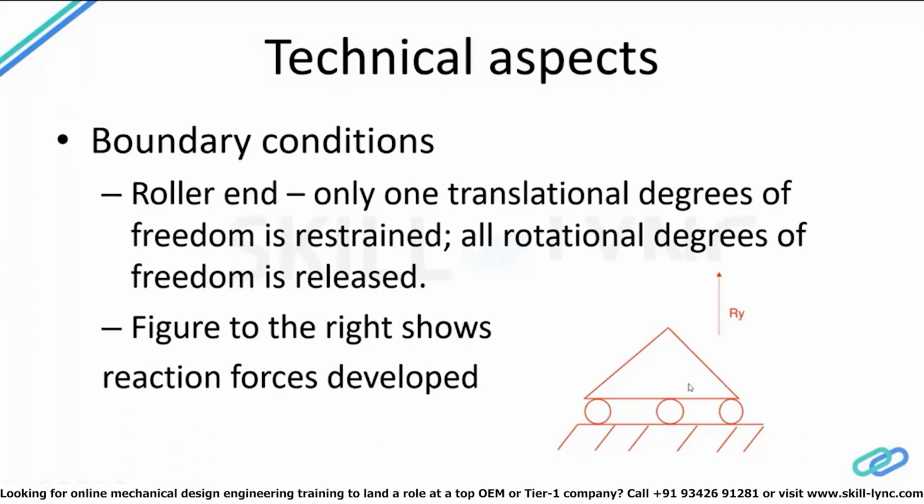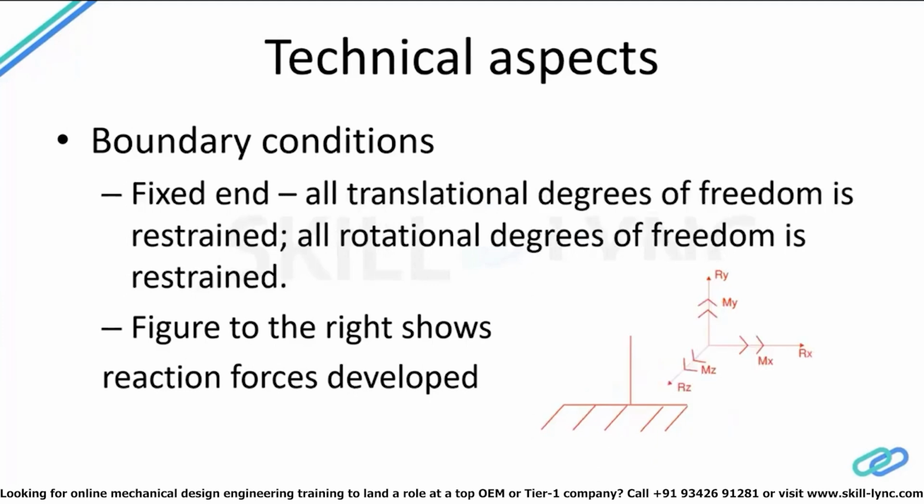A good real life example of this kind of support would be an expansion joint, with a beam crossing the expansion joint in a structure. In that case, that beam has to be seated on a roller support, like a bearing pot or something. The reason is that the intent of an expansion joint is to not transfer any lateral loads induced in the two structures from one structure to the other. So you require this kind of support there, so that the member spanning across the expansion joint does not transfer any lateral force from one structure to the other. That's one example of a roller connection. There are a bunch of other examples as well, like in the bridge industry. So that's a roller support.